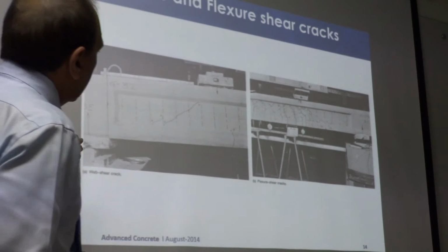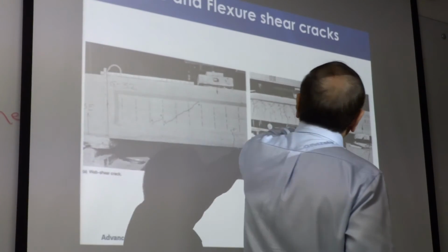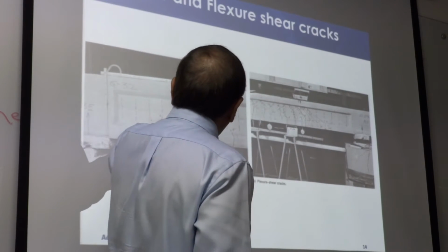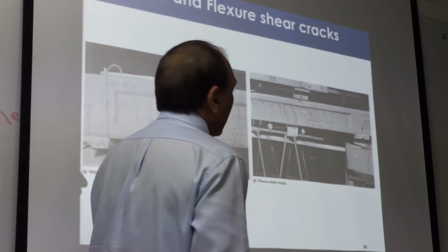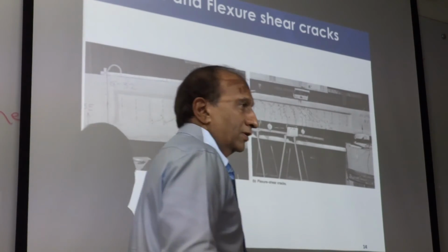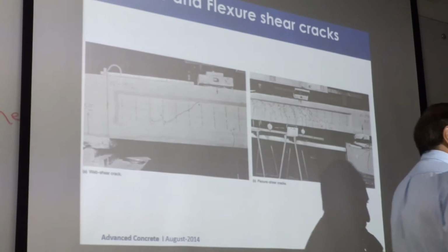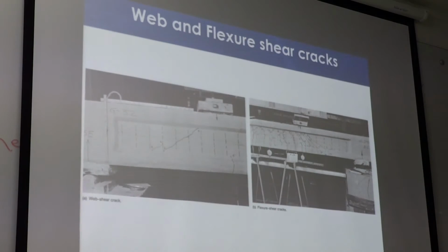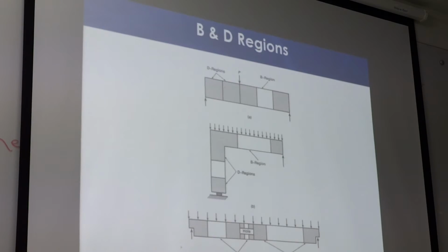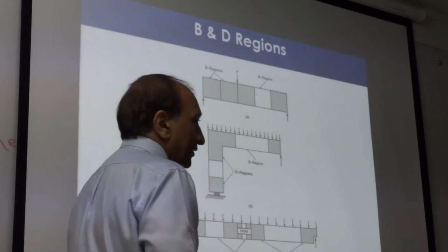These are some of the samples, cracking pattern you can see from here, tension developing, shear failure, pure shear failure, falling down, and then this is all coming because of those principal directions and tension and having no reinforcement. Other problems that we will talk about later, just to give you an idea that we are not done yet.